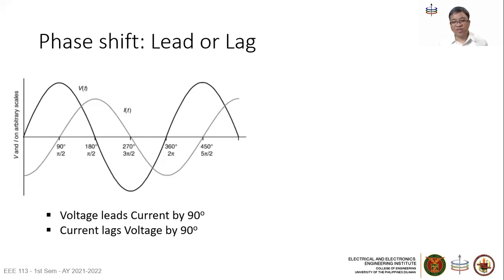Of course, we have this warning here. Because our eyes are used to reading from left to right, some of us may mistakenly think that this current leads the voltage by 90 degrees, but that's not the way to do it. Don't do that. So we look at the key state: either we look at the zero crossing here, positive slope, and compare the two, which one happened earlier.